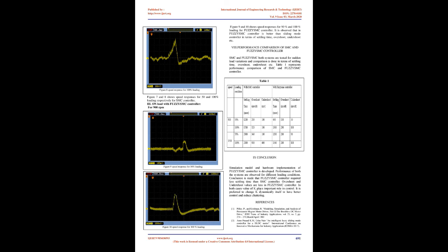The controller is the heart of the hardware system. In the proposed system, the PIC18F4520 microcontroller from the PIC18 family is chosen. It is a 40-pin IC. PWM pulses are generated from the controller and given to the drive circuitry of the inverter. The PICkit3 programmer is used in the proposed system to program the controller.